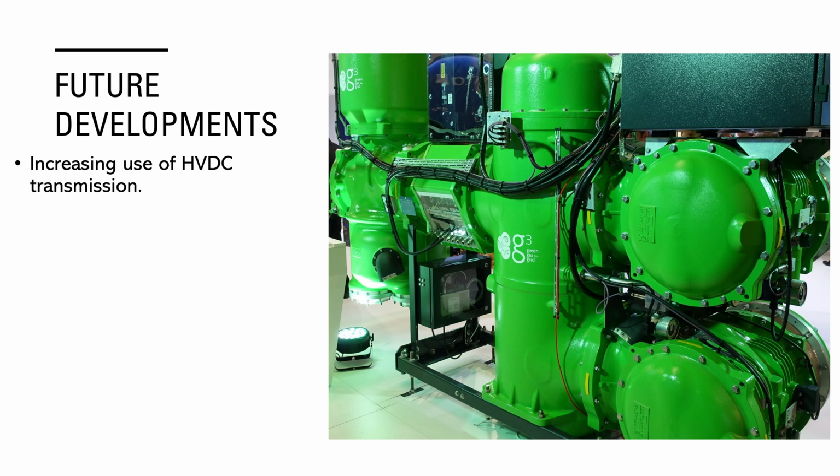And because of that, we need to have HVDC. We are going to see increasing use of 66 kilovolt inter-array cables and maybe even higher voltage. I mean, now we've got turbines in the 15 megawatt class being specified for farms. So within 5 years, we'll see 20 megawatts, then we're going to see 25, maybe even 30 megawatt turbines. They may need higher voltage.